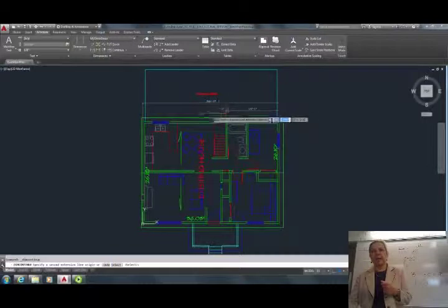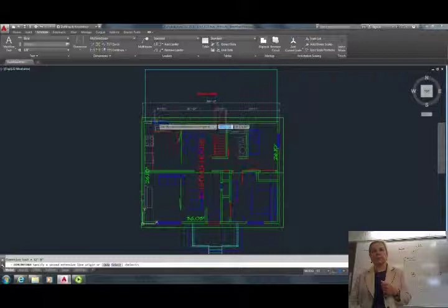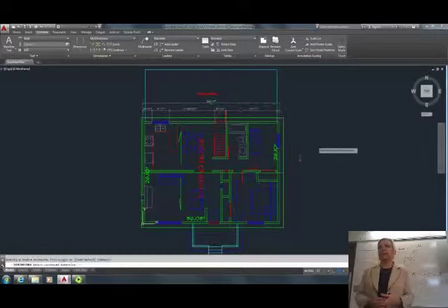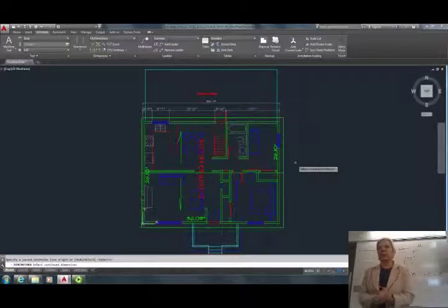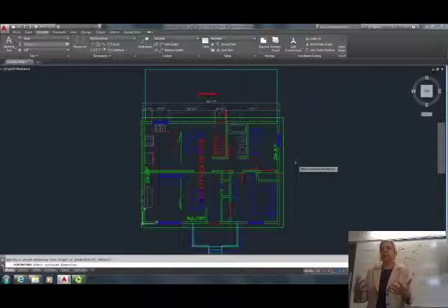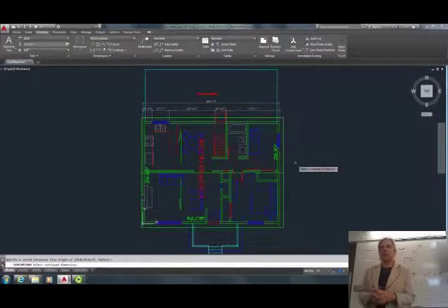You should be zooming up as you do this and making sure that you're picking up the right points of your string, and you have the string of dimensions, and if you followed everything correctly, we don't see any fractions. I'm not questioning how they're going to come out. They're going to come out perfect, but I might be looking for some problems, and I see one. Do you see the problem? In my dialog boxes, I have gone through the motions of changing it to the Roman style, but it did not happen. It's still coming up this mushy, unclear double line text.